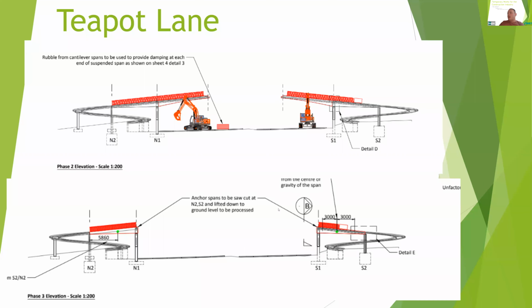next one. Once that was lying on the ground, we then processed this, broke the slab, broke the bridge back to the support, or near enough to support, and then the back spans were lifted out. Now, they burnt through the anchoring point here, and lifted out the back spans with the same crane. The reason that was done is because, again, we were keeping this pier and this pier here.